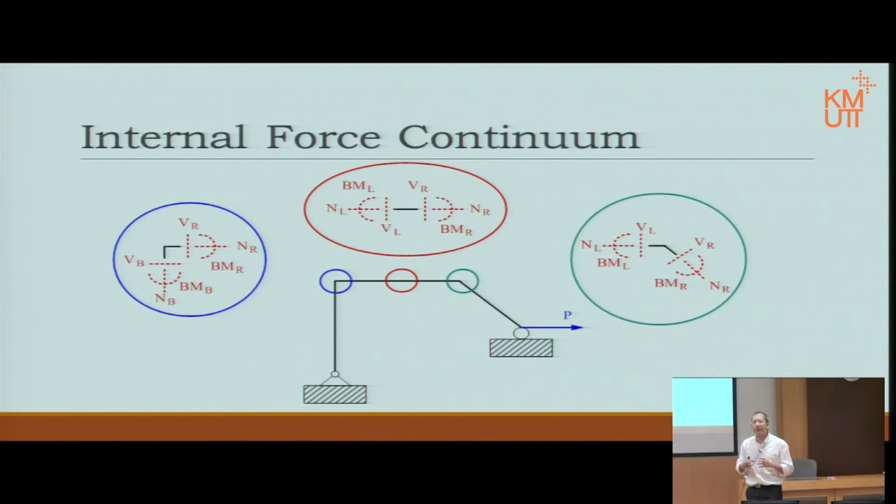However, since we define shear force and axial force according to the alignment of the member, you cannot continue the same alignment for the shear or axial force if the member changes alignment. Therefore, only the shear force continuum and the axial force continuum are disrupted, but the total force system is still continuing. It's still the same continuum because in this case there is no force or moment adding in or subtracting out. It's just because of the definition that it broke down.